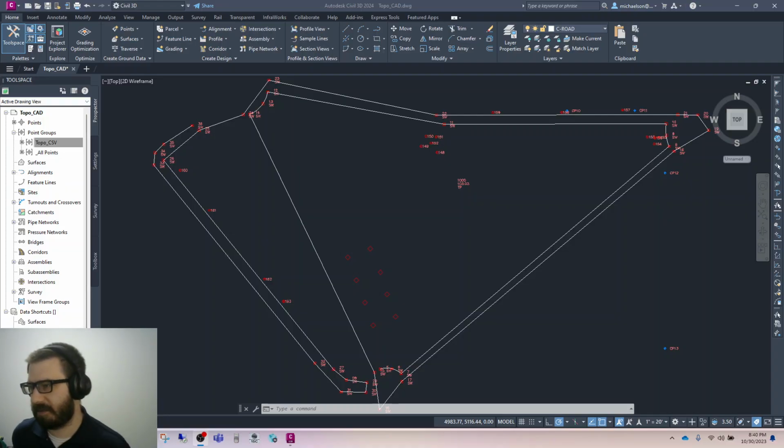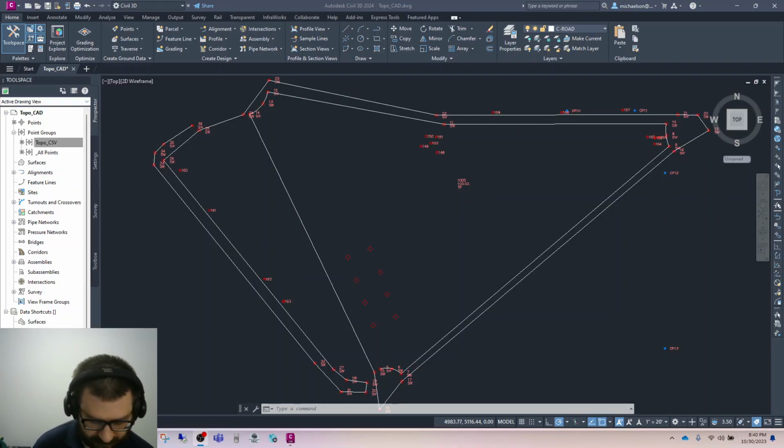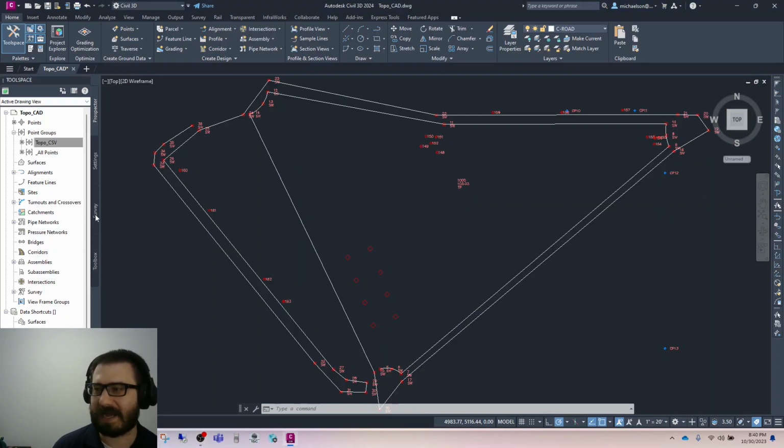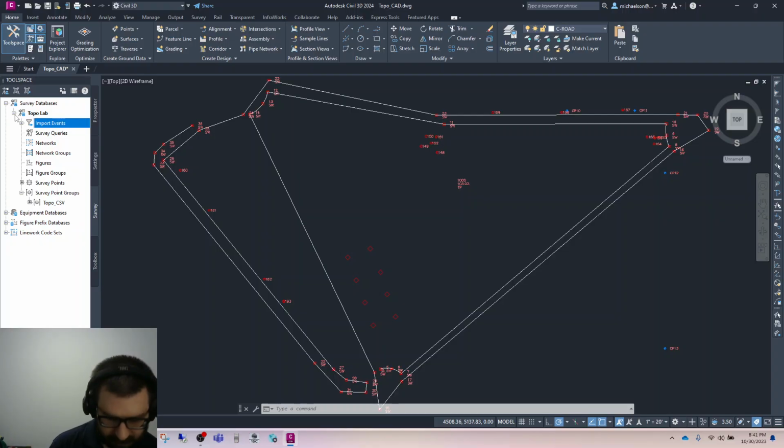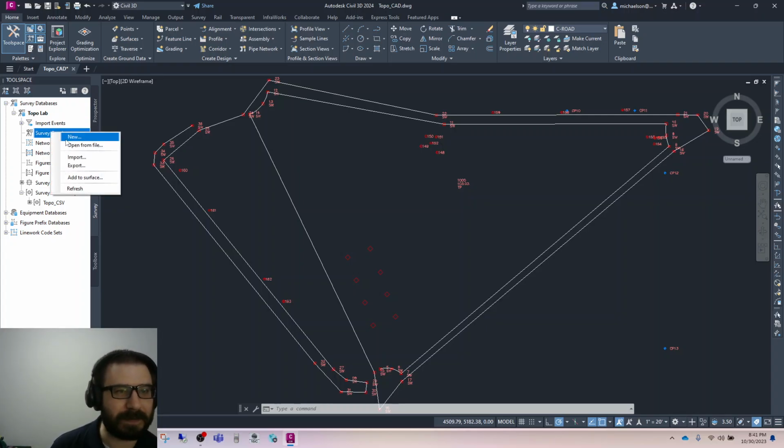Okay, so now we're going to generate our contour lines. And so this is hopefully where we see if we've collected enough data to get a good contour plot for our survey. So we're going to go to the Survey tab. Again, like I said, a lot of the magic happens in this tool pane over here on the very left. And we're going to go to Survey Queries. Let's see. In the Survey tab, where is it? Oh, there it is. I couldn't see it, but it's what happens when you're doing this live. Okay, so we're going to have a new one.